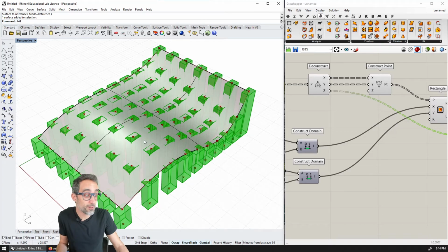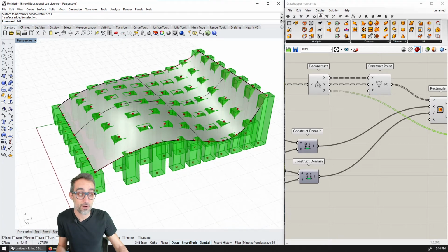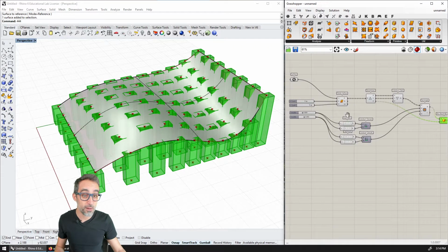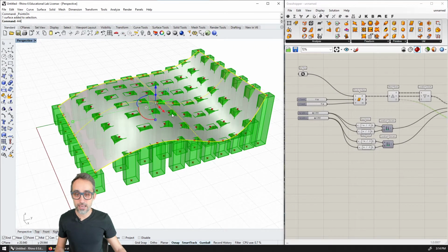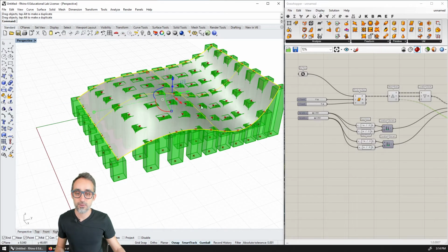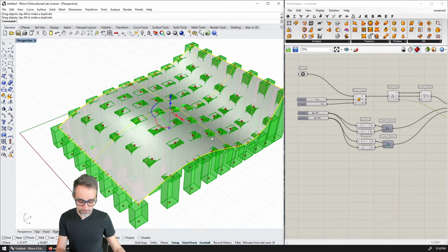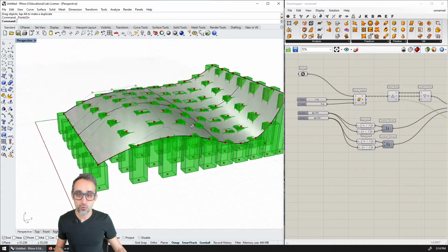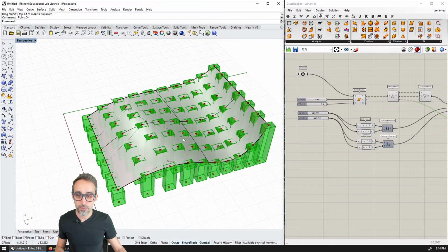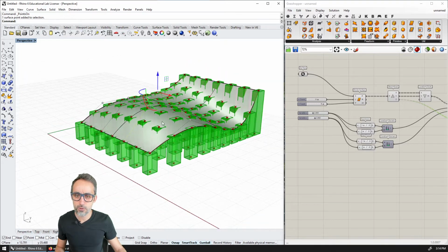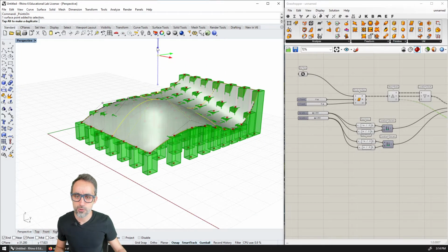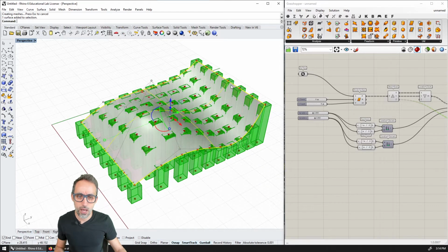And what's beautiful about this now, as usual, because this is parametric design, because all the relationships are parametrically bound to each other, what I can do is I can modify the original surface. So for example, I can just move it anywhere, and then all the blocks will move correspondingly. I can press F10 to turn on the point cloud, and then decide, I want this point to be much higher. Whoa, so I'm going to create a larger bulge here.